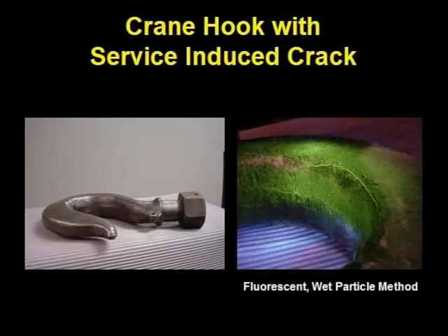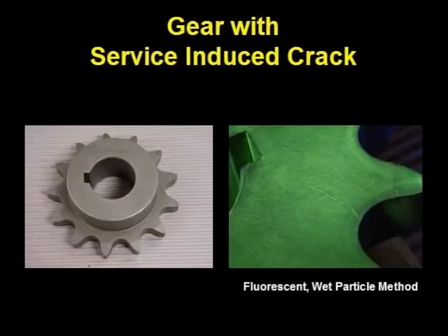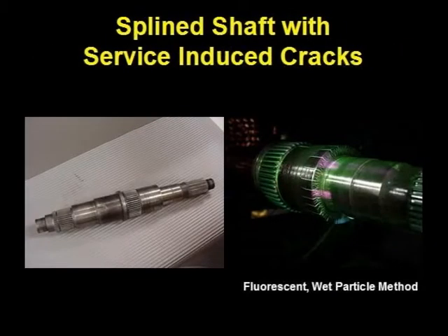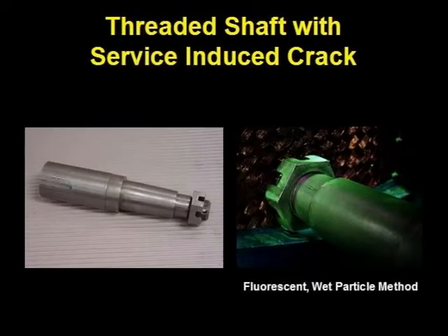This slide illustrates a crack detected by fluorescent wet particles. This slide illustrates a service-induced crack in a gear. This slide illustrates heat treatment-induced cracks in a drive shaft. This slide shows rather severe service-induced cracks in a splined shaft.